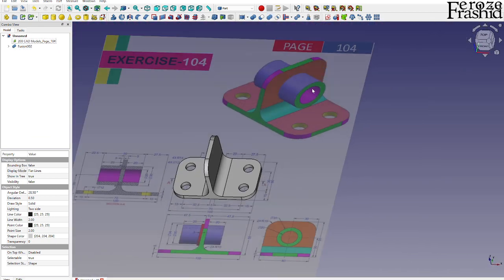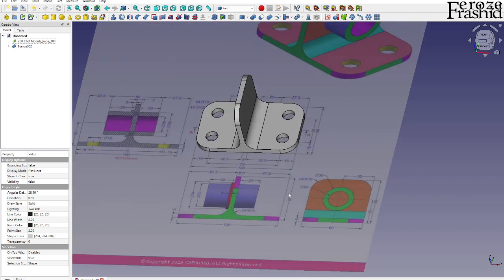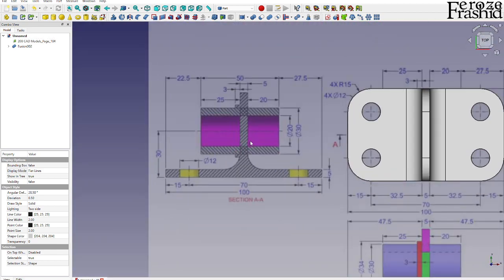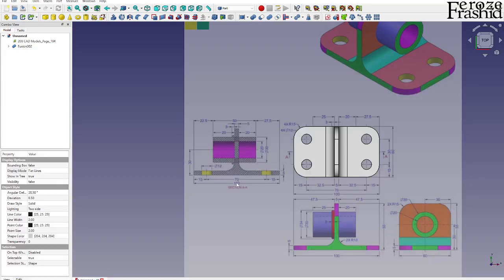Now let's go ahead and think about this tube. The first question is, does this hole go through from here and there? It does not. It does not look like it goes through here. We can take a hint from the color, but to make sure we are not doing anything wrong, let's look at this cross section, which is at section AA, which means that the line was drawn here. And then it says the wall is thick, solid all the way across.